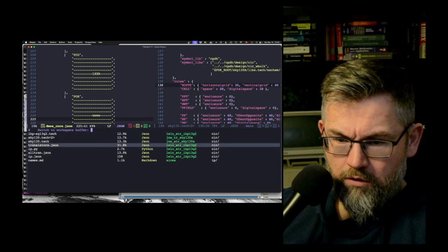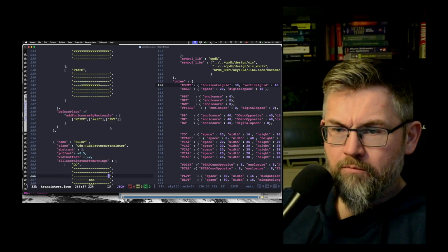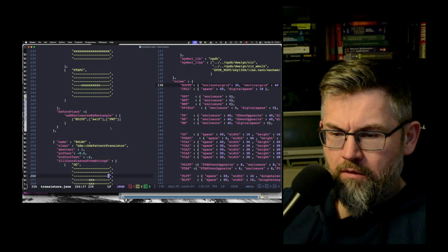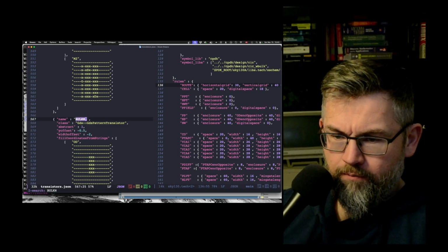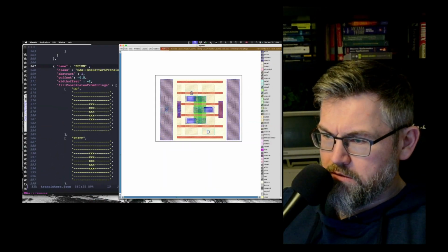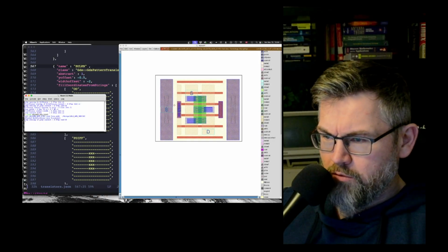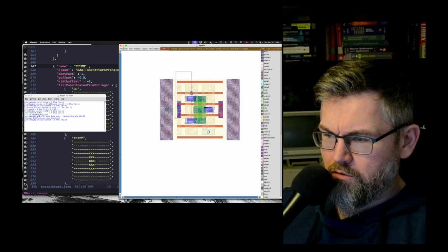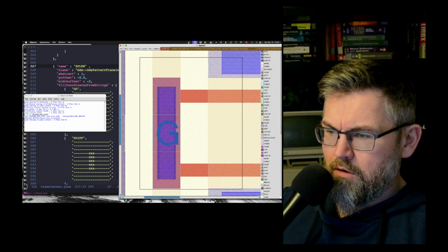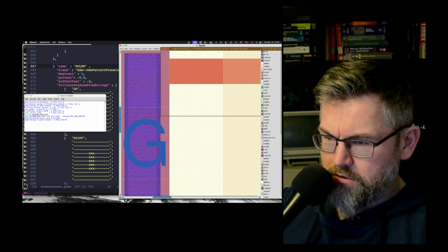Let's see, we were looking at transistors, right? And we were looking at bulk N. So let's see. The problem is that this... which one is it? So the poly overlap of this contact is too small. But which direction? Probably in the X direction.